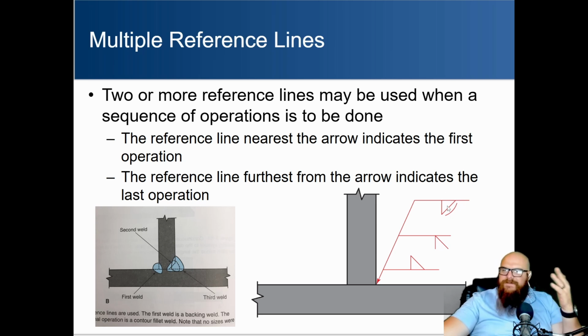The third weld is also underneath. It's telling us it's a fillet weld. We're going to fill in that groove from the previous one, so there's no need to bevel it. And we have this little arc here that's indicating that we want that weld to be a little bit convex. So we actually want it to be a little bit rounded off at the end.